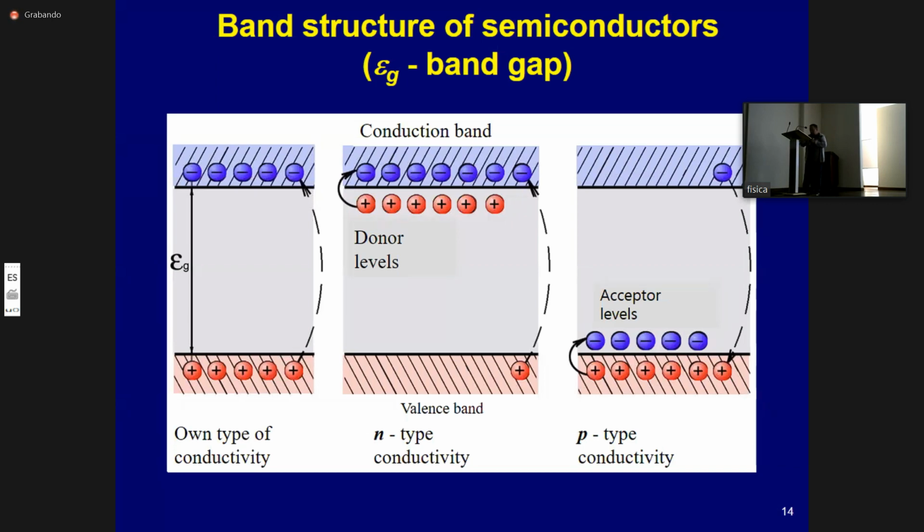But we have to solve this problem. In order to use a semiconductor as an ionizing radiation detector, it is necessary to create a layer depleted in charge carriers. It can be electrons or holes. Then the ionizing particles, passing through this layer, form electron-hole pairs in it, by analogy with the ionization chamber. Under the action of an external electric field, charge carriers reach the electrodes, which is recorded by a current pulse.